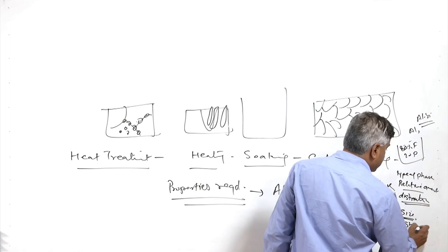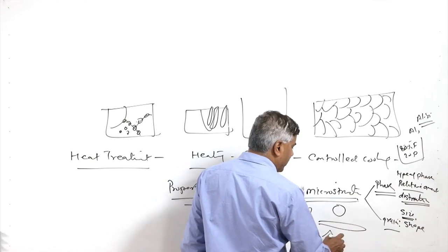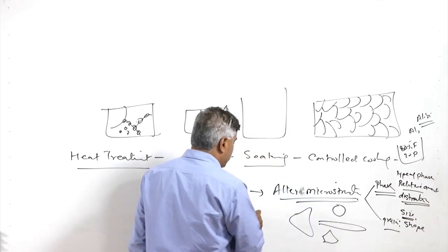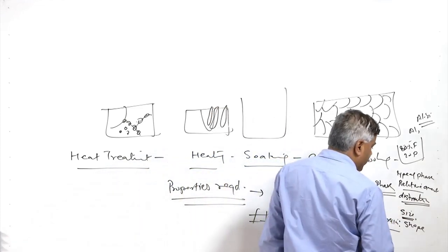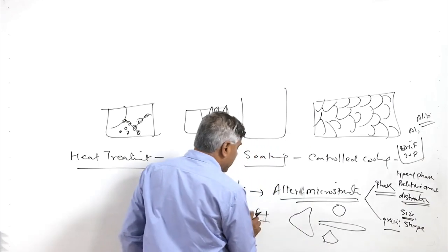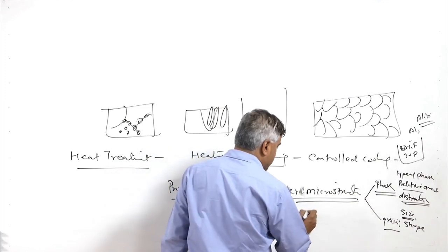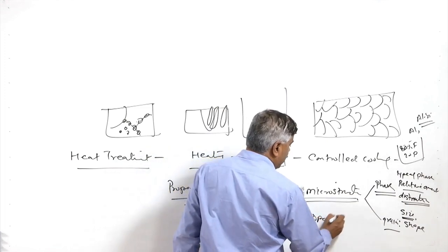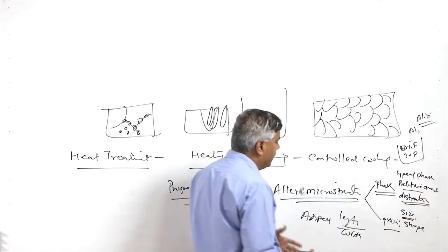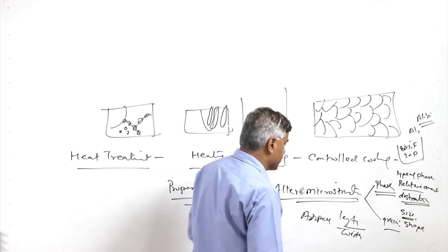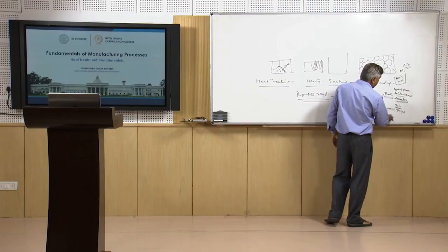Then the shape of the grains: the grains may be needle shaped or circular shaped or polyhedral or very irregular or star shaped, or in Chinese script form. So, there are different shapes, and that shape needs to be identified. The general way to identify the shape factor is the aspect ratio, wherein the length to width ratio is used to define the shape aspect. Needles will have a greater aspect ratio as compared to the circular geometry or spherical shaped phases.